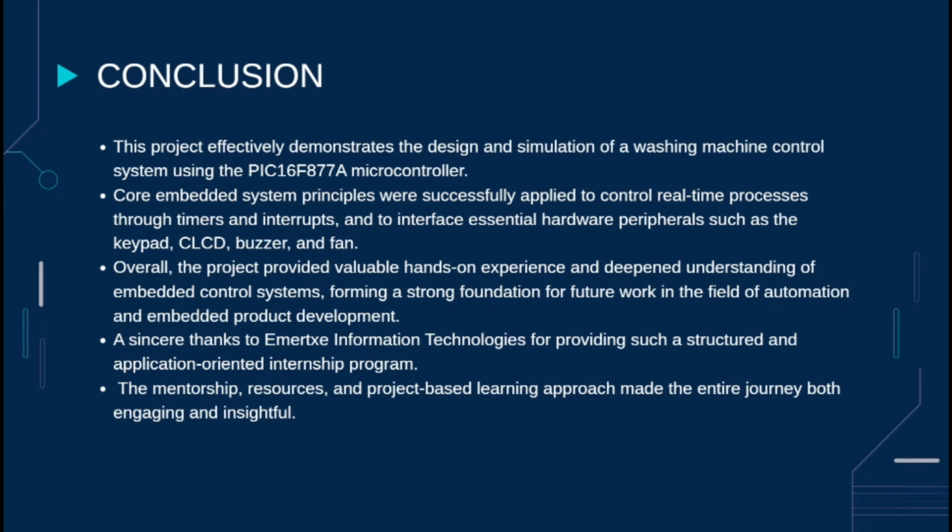Through this simulation, we have seen how core embedded system concepts like timers, interrupts, and peripheral control can come together to replicate the functionality of a real-life appliance, that is washing machine in our case. Working with the PIC16F877A microcontroller and using tools like MPLAB X IDE, XC8 Compiler, and PICSIMLab gave a solid understanding of both the hardware and software aspects of embedded development.